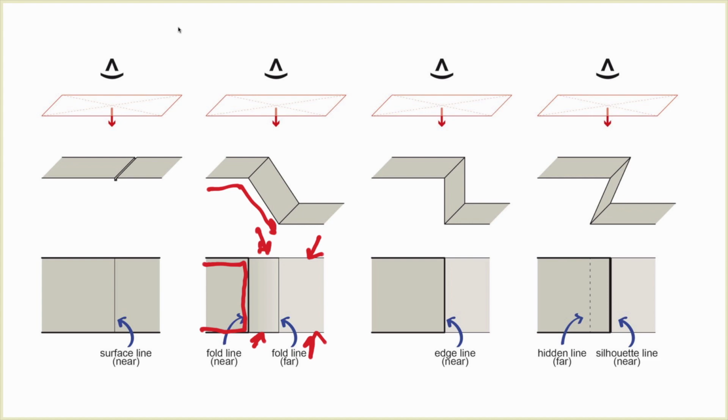In this particular case, we're dropping straight down. So we've got this here as one thickness, then this, because it's got a drop, is a little bit thicker. So we're showing that even a little thicker to show that edge. And then we have the thinner lines right there and right there that are further away. This last one we fold under, and so we're using a different line type. Here's where our hidden line comes into play. In order to tell that it's folding under, we draw that little dashed line right here so we know where that fold is. Likewise, this is our thickest line yet, right along that edge.